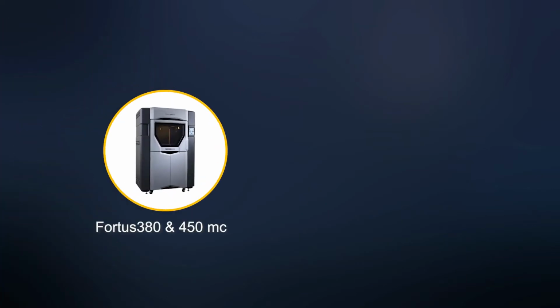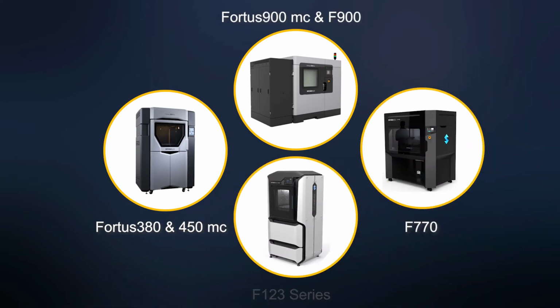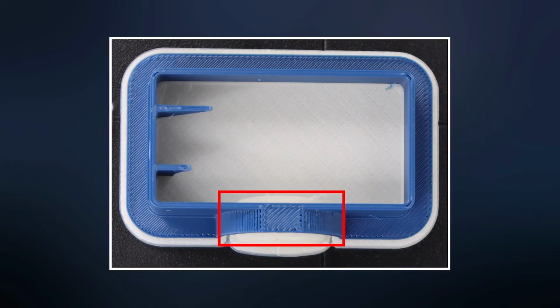The Fortis 380 MC, Fortis 450 MC, Fortis 900 MC, F900, F770, and the F123 series printers with the latest versions of their printer software can fill these air gaps when used with the option Use Variable with Fill. Using this feature will make the part stronger and more rigid.